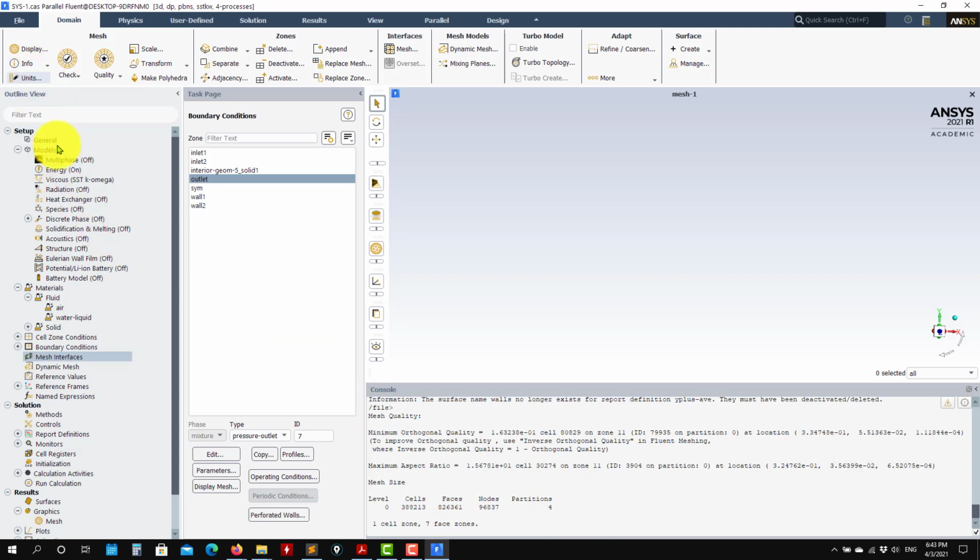The mesh size here, in info, you see that we have almost 400,000 cells, so it's a much larger problem. If you don't use Symmetry here, you will see that this will go to twice this, okay? So this is the advantage of Symmetry, but remember that Symmetry can sometimes be dangerous because you can suppress one stability mode. In this case, we can take that assumption as the right one, okay?